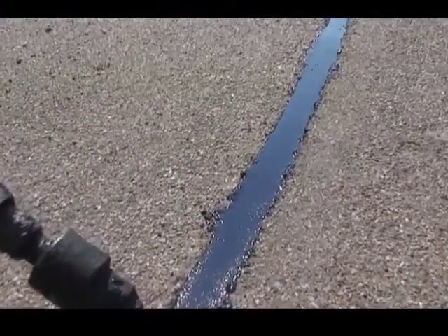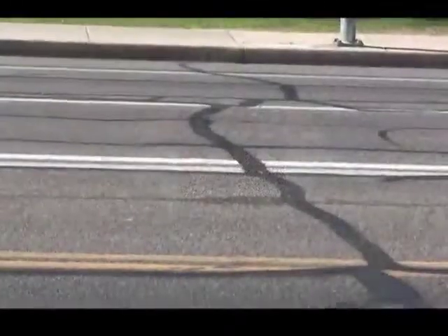After the crack reservoir has been sealed, the sealant will expand and contract within the routed reservoir. The sealed crack is then effectively preventing the loss of sealant and non-compressible material from entering the crack. Crack sealing will usually last 3 times longer than simple crack filling. With the added cost of routing and router maintenance, the cost for sealing these types of cracks is much less than just crack filling on an annualized basis.